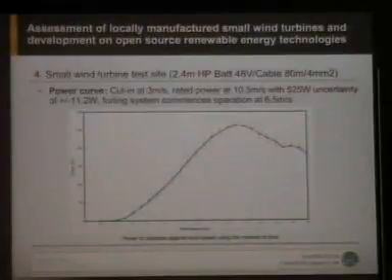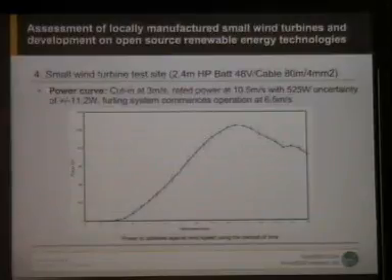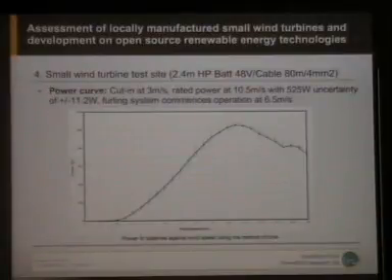okay. So this is the power curve at the test site. We'll go to the test site on Wednesday. Okay, you've seen a lot of these. One thing that's interesting is that the furling system starts to operate at 6.5 meters per second with just a little bit of an angle, but kind of preparing to reach the maximum at 10 meters per second.